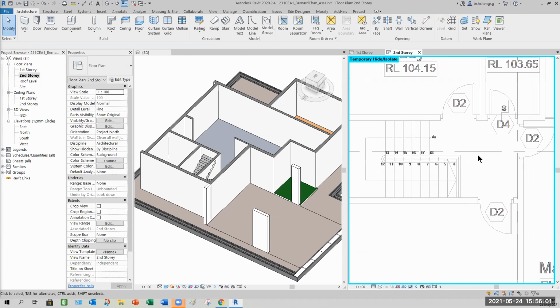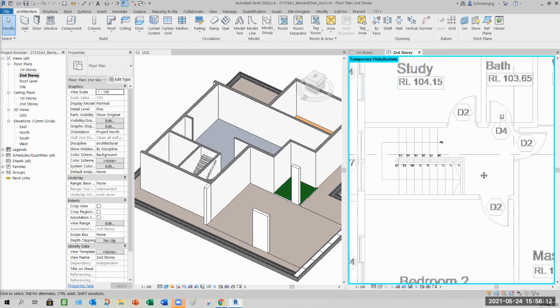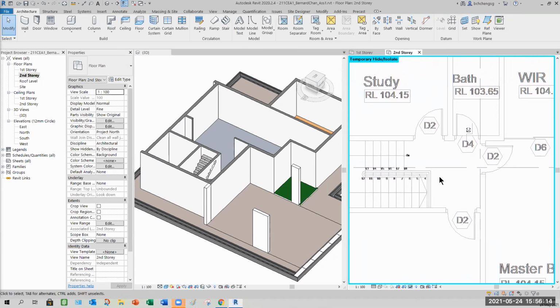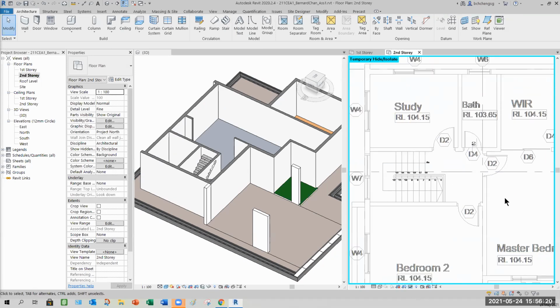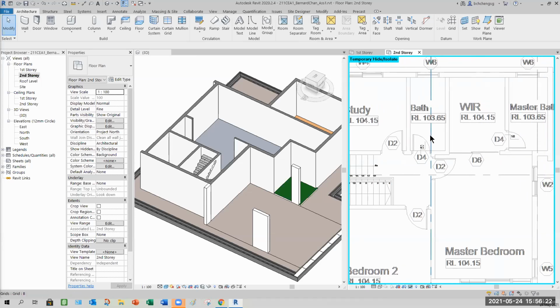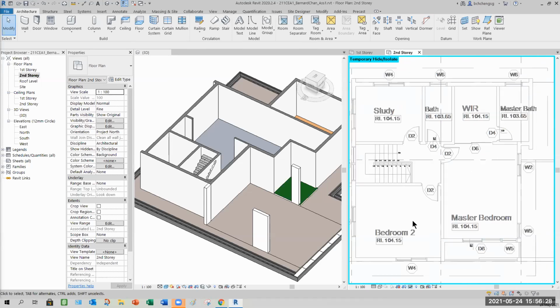By looking at this, my slab line is actually here to here to here. And this is my landing slab, or your common area. You can call this a common area. So how to create this slab here? Level 2. From here onward, everywhere should be wood finish. Only the bathroom is not. This is your walk-in wardrobe and all these individual rooms. Like what we do to create our slab, settle this one first. If this one is settled correctly, then we do the rest.